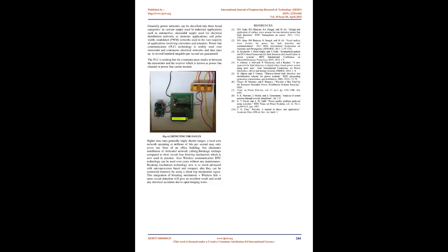It auto-detects the hardware connected to the serial port. It also auto-detects the chip inserted and bytes used. The software is developed in Delphi and requires no overhead of any external DLL. The programmer connects to the computer's serial port, COM1, 2, 3, or 4, with a standard DB9 male to DB9 female cable. Baud rate 57600, COMX automatically selected by the Windows software. No PC card required. After making the necessary selections, the Auto Program button is clicked as shown in the figure below, which burns the selected hex file onto the microcontroller.